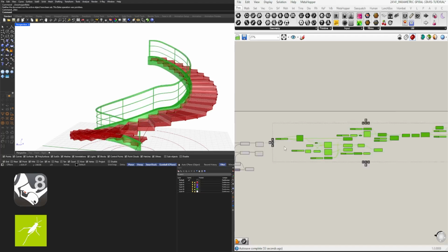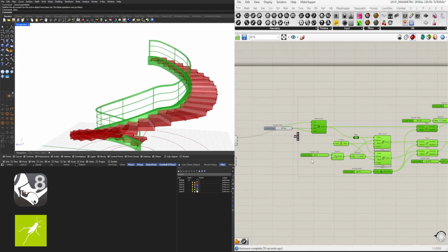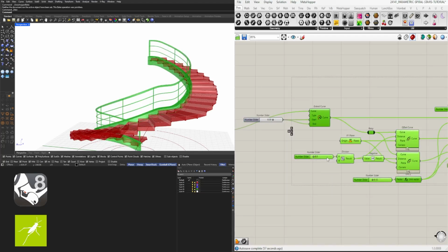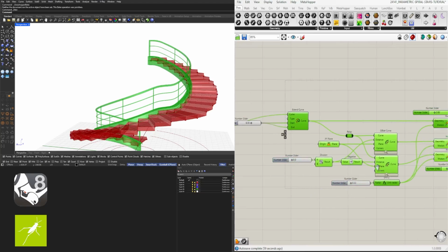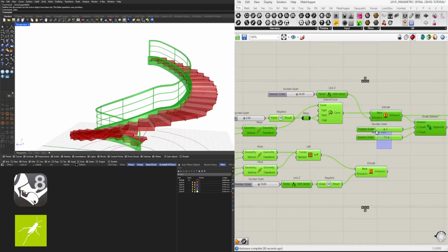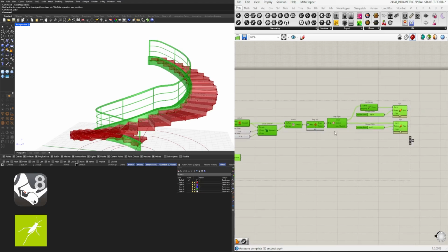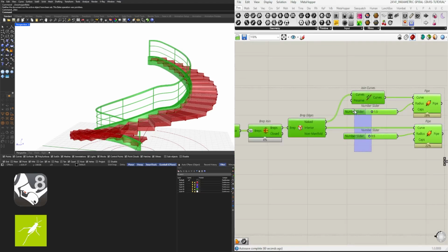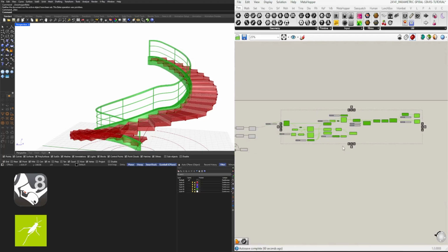So we'll select everything, holding down Control, or if you have a Mac, it might be Command, to deselect the sliders because those are going to be shared. And if we don't copy those, then it'll copy the components and not the sliders, which makes it a lot easier for us to change the design, not just have one side change as different than the other.